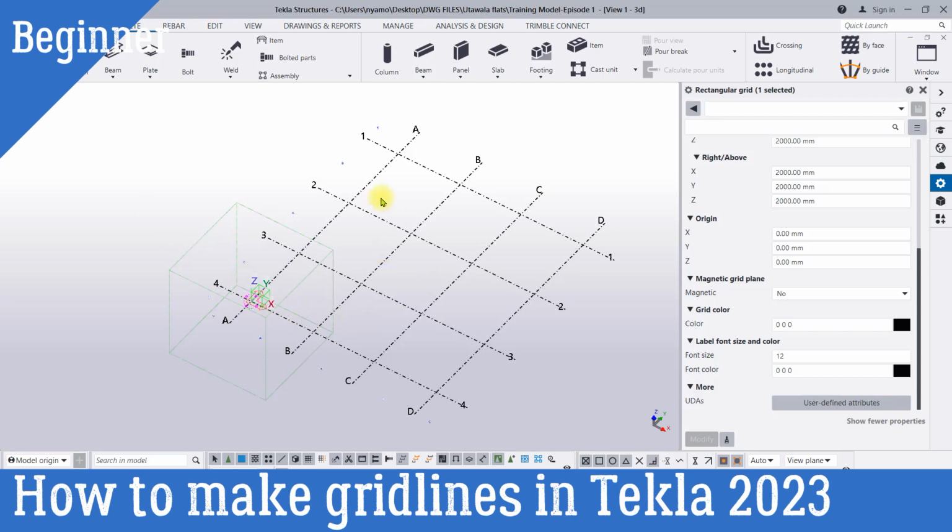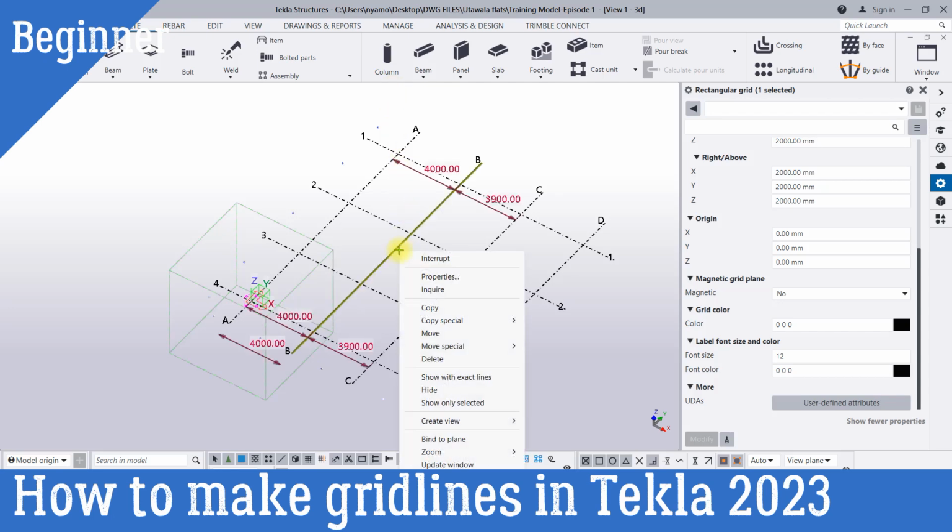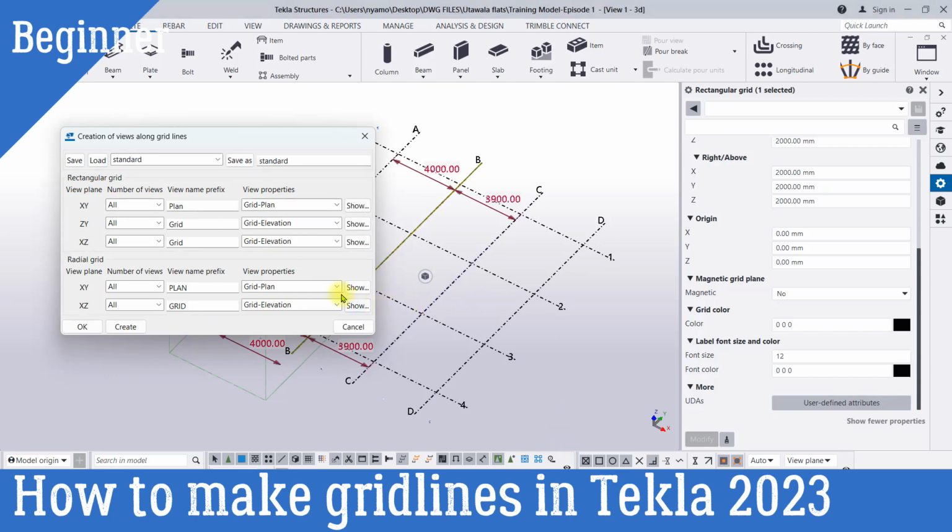So I want to convert these grid lines into 2D so that you can input your elements once ready. For you to convert these grid lines into 2D format, you basically need to click on one of the grids, right click, and then go to create view, and then create along grid lines, and you'll have a wizard like this, which is displayed.